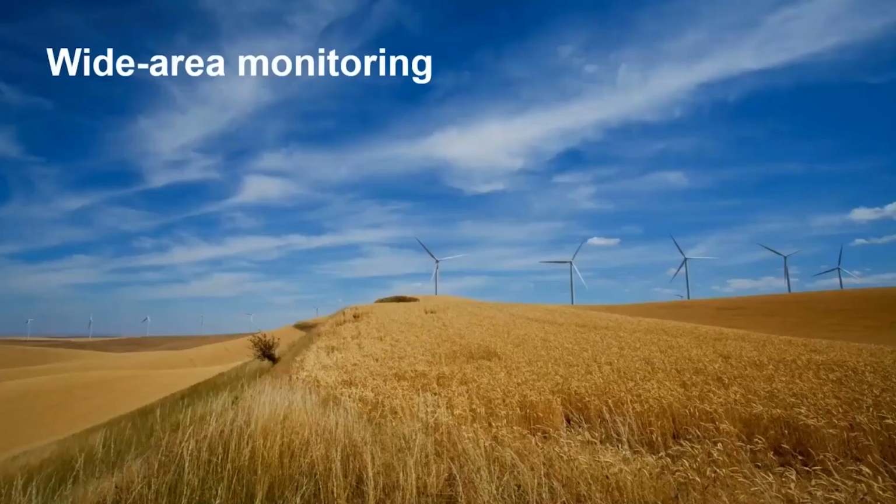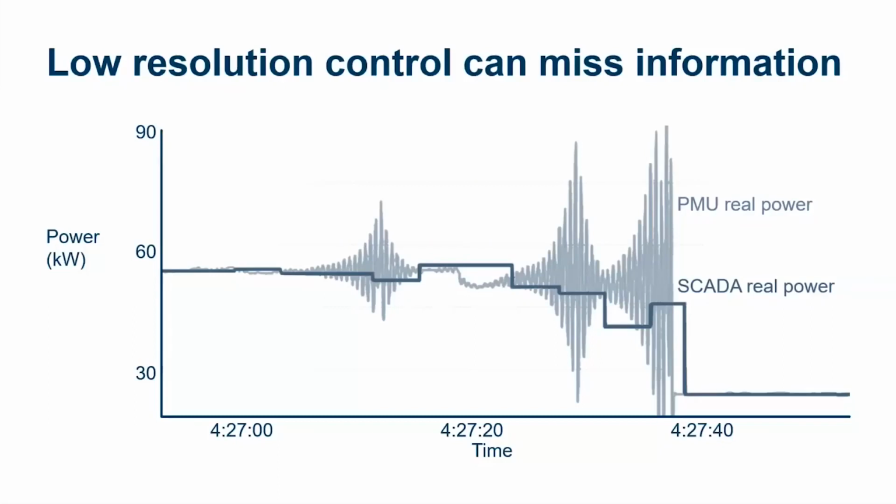Now that we've looked at wide area control, let's take a little bit deeper look into wide area monitoring. A typical SCADA measurement might not be able to provide an accurate representation of a power system event. Most power system operators rely on SCADA data as the primary method for communicating power system data for visualization, analysis, and operational decisions. SCADA data are usually scanned asynchronously and updated once every second or so.